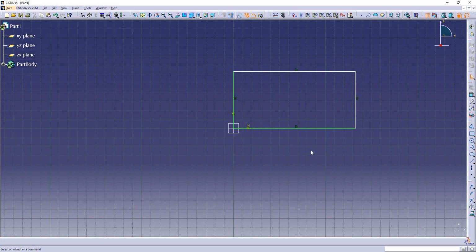Similarly, yellow represents a non-modifiable element. This indicates that these elements cannot be graphically modified. Similarly, gray represents a construction element. These elements are used as positioning references. The red-orange indicates the element is selected. The purple color indicates too many dimensions are applied to the geometry, and the brown color indicates that some geometrical elements are overdefined or not consistent. As we create different profiles, we may come across all of these colors.